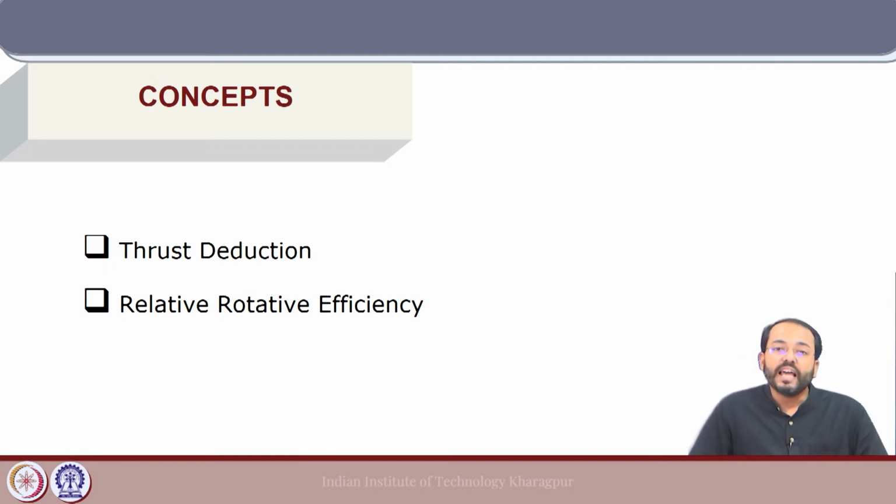So, the main aspects of these interactions are the wake behind the ship hull at which the propeller operates, and then the propeller accelerating the flow in the aft part of the ship, and the relative performance of the propeller in the open water and behind hull, which gives rise to all these factors that we are studying.